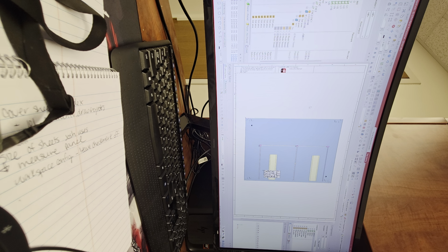But let's just say just grab it from the library. Let's just drag and drop it into the MP folder. If you scroll up a little bit, yeah, that one right there. It looks like it's under the E folder, E1. That's the one that we just planted. You can grab it by the E1, you don't have to grab it by the model, just to drag and drop the part. And there's your ground bar that you need to place under your VFD.